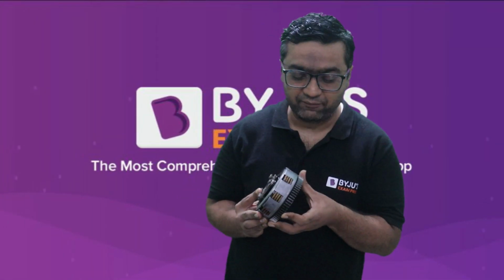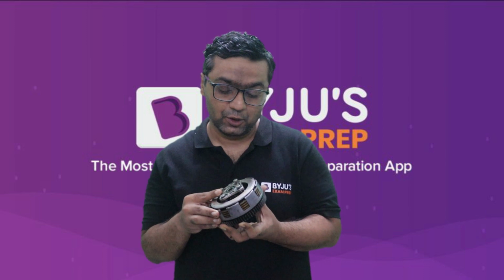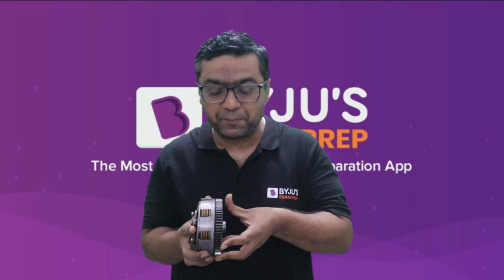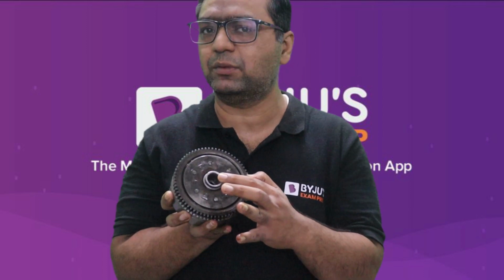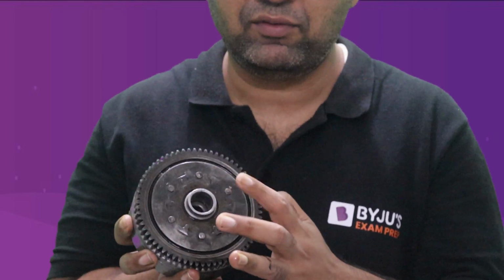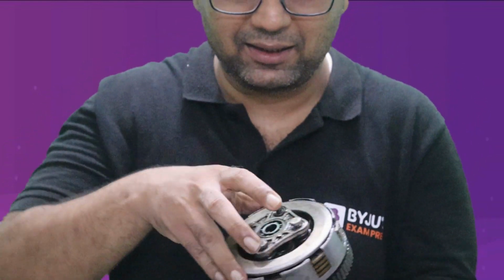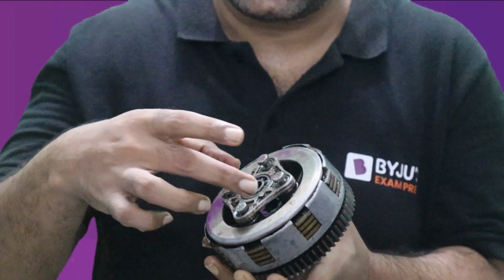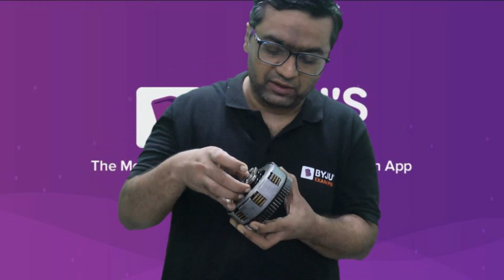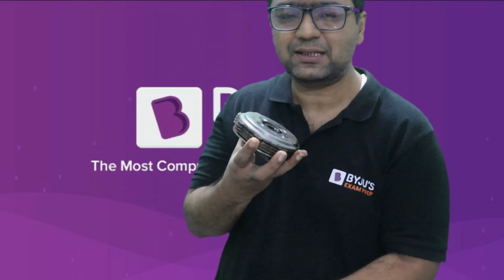So guys, we have a multi-plate clutch, and this has been disassembled from the engine assembly of the bike. If you see there, you can see there is a hole. Here we have the shaft which is coming from the engine side, so engine power will be coming. And then you can see that here you will have another shaft which will be coming from the transmission side. I will be taking this out. So I am keeping this aside.